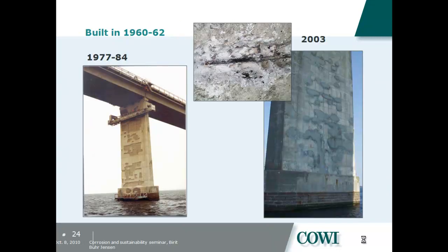This is a school example of how that can look. This is one of our Danish marine bridges that was built in the very early 60s. Shortly after, we had extensive deterioration due to corrosion. You can see the extent of repair that was done based on a visual inspection and where the delaminations were. Doing a special investigation of these parts, we found corrosion in so many of those repair zones, just in the circumference of them, supporting this